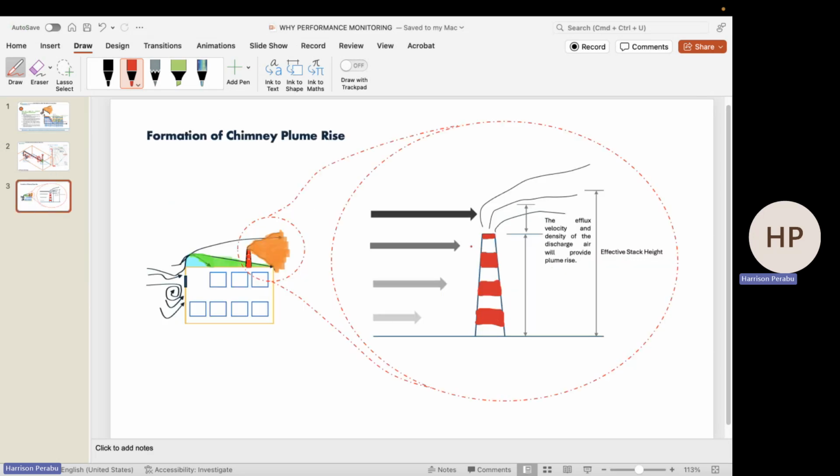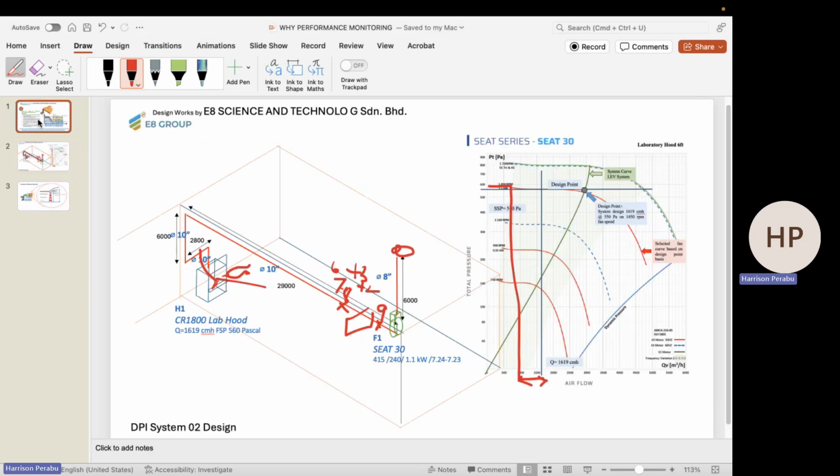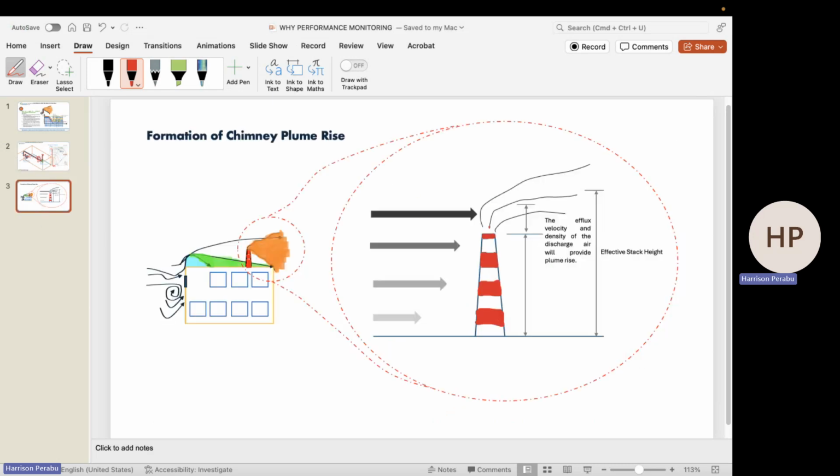From the DOE perspective, or from the environment perspective, now the basic flow rate, when resistance goes up, efflux velocity drops, the flow rate of the overall system will drop. Let's say our baseline efflux velocity is 10. We don't want it to go below 8. If you go below 8, let's say it becomes 7.9, what will happen? There is a possibility of downwash to take place.